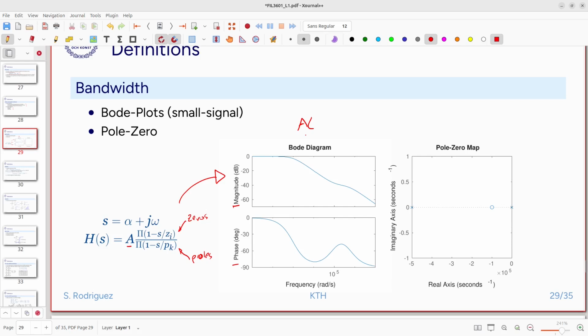Very useful in analog design, we are also going to use pole-zero analysis, in particular for compensation purposes. It is much easier to use the pole-zero than the Bode diagram, but both are extremely important. Very seldom do we do small calculations using the Fourier representation, also when we are not interested in the transient part.